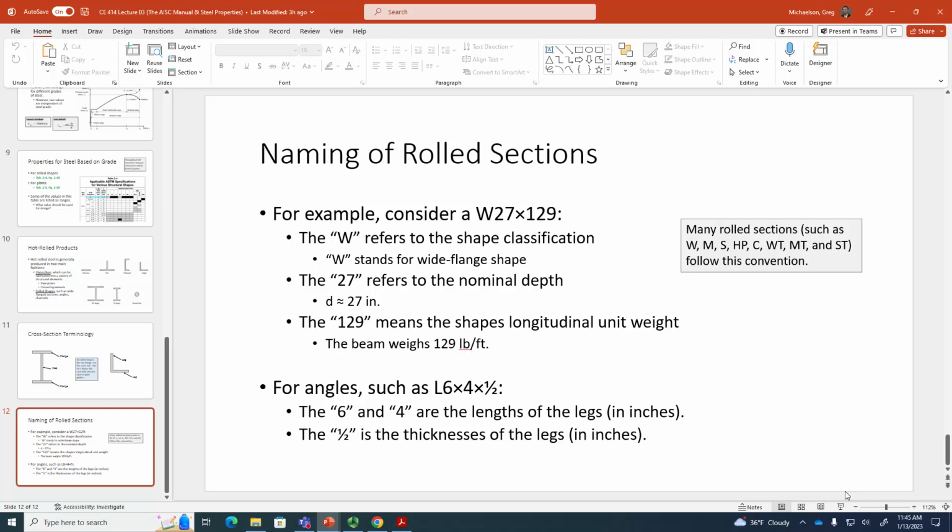What happens if you take a 1/2 inch diameter bolt and try and stick it in a hole that is a 1/2 inch in diameter exactly? It won't go in, right? So the hole has to actually be drilled a little larger to accommodate the bolt, right? How much larger? That might sound silly, but those are details we have to account for when we're detailing steel connections. So there's a difference between the bolt diameter and the hole diameter. It might sound silly, but those are important dimensions.